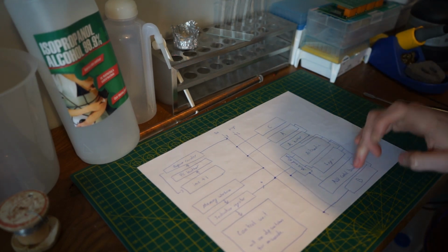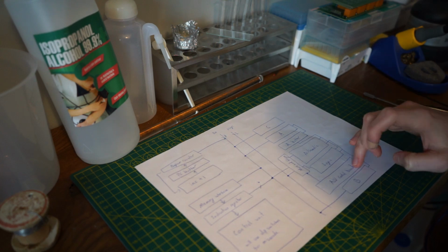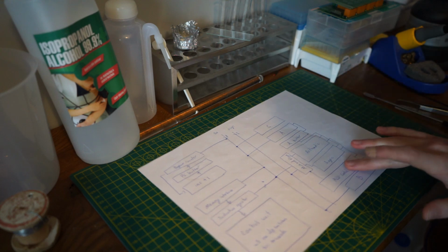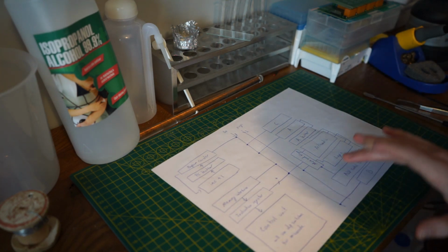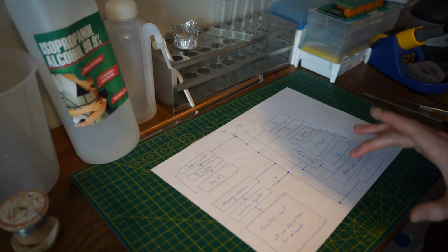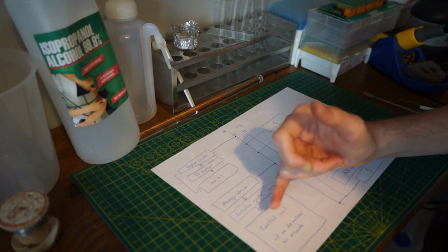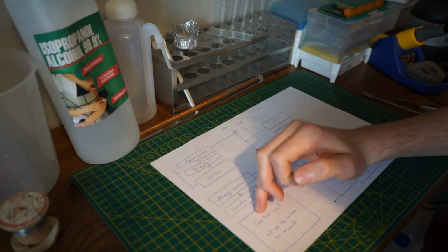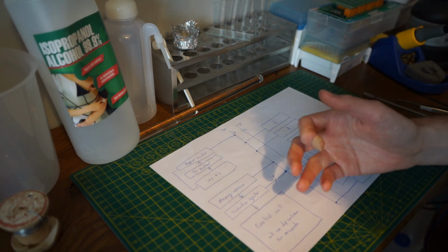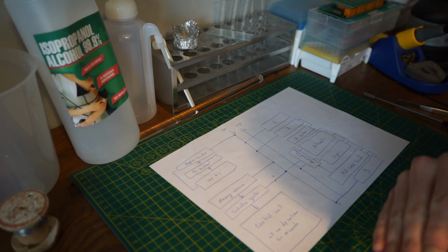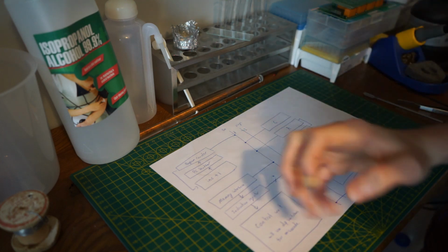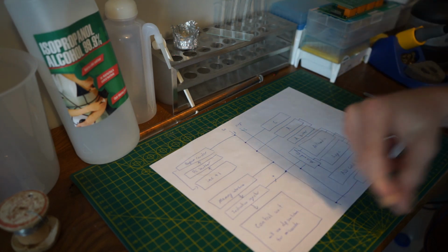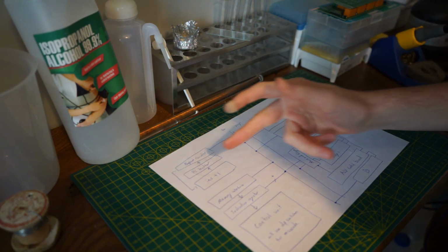We have our control board for the ALU. This will take a 4-bit or 3-bit input, which will then determine how the sequence happens in the ALU. We'll also have a control unit. I'm going to use DIP switches with a decoder to easily be able to reprogram it. So you take your instruction register, and your instruction comes in, which is 4 bits, and this will be decoded into 32 lines. The 32 lines will each have 2 lines per instruction, because there will be two clock pulses for the execute cycle and then 2 previous ones for fetch and then decode.